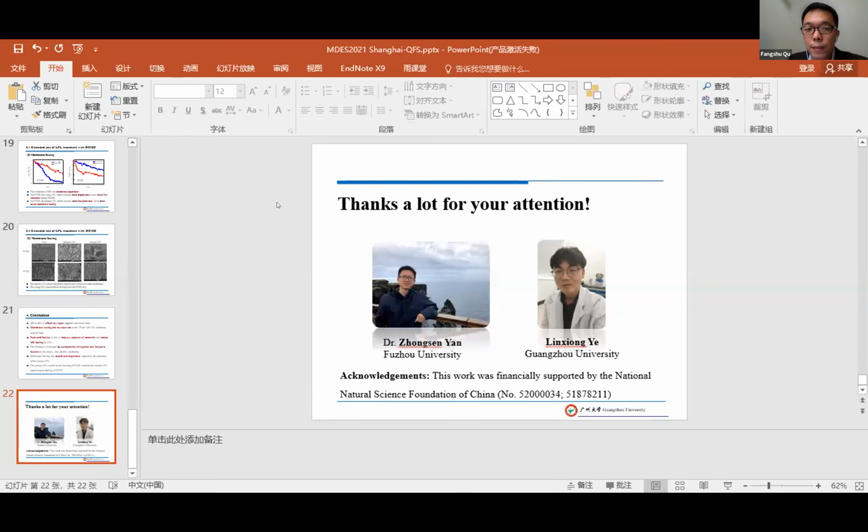Okay, I think he means some characteristics of the landfill leachate. The COD concentration is about 2,000 milligram per liter, and the ammonia concentration is about 200 to 300 milligram per liter, and the temperature of the MD we use is 60 degrees centigrade. Okay, is that okay?